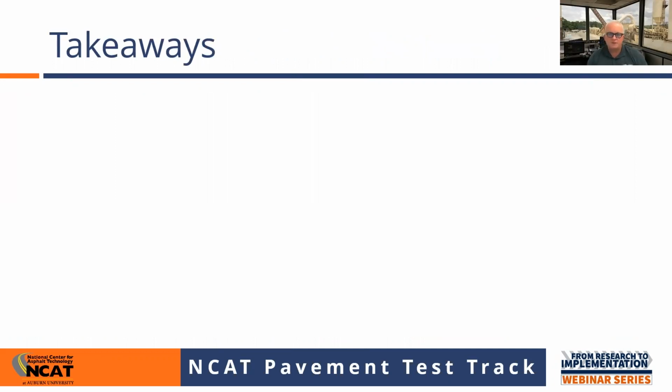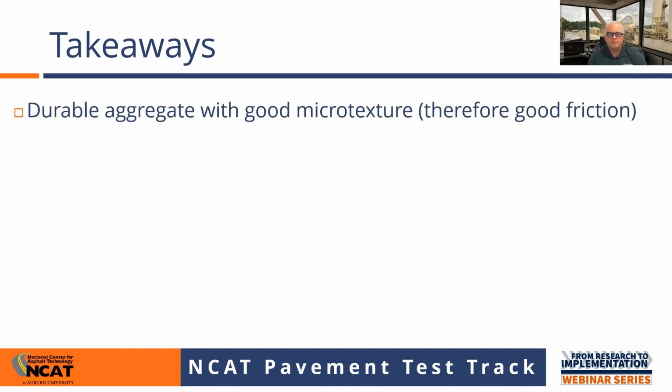So we got 15 minutes to go before we hopefully can get into some questions. But I wanted to end up with some takeaways. I always like to have takeaways at the end of these webinars. As practitioners, what can y'all take from this and consider implementing in your practice, implementing in your specifications? When you do these surfaces, you need durable aggregate with good microtexture, and microtexture is the grittiness that you feel in your fingers.